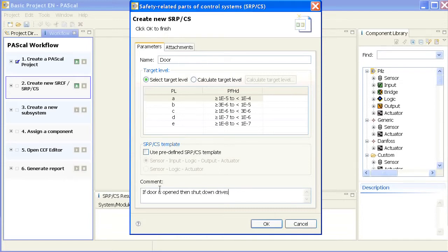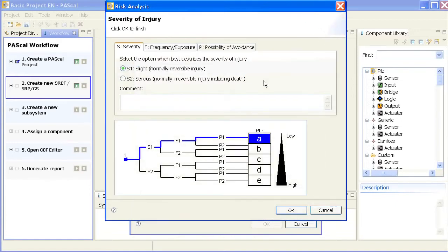So that's the basic idea of the safety function, but one thing to do is I need to select the target performance level. If I have a C standard, machine standard, I might be able to take the target level from the standard to select, let's say, a PL, or I can use the risk graph from 13849 to determine the safety function performance level.